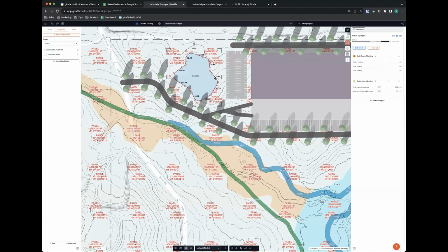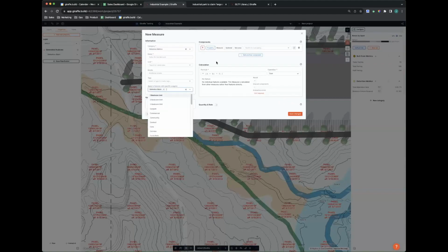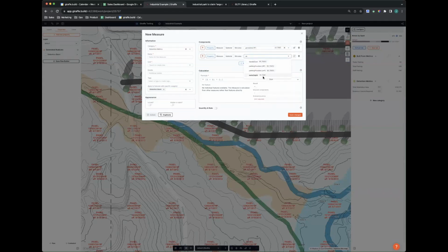And then let's go and build a calculation that tells us the total volume of water that we've catered for on the site. So we'll do a new calculation. It relates specifically to the detention basin, and it's the gross area multiplied by the depth. Now, again, very simplistic calculation. We could add in a trapezoidal calculation if we want. Again, that's probably more than we're going to need to do here on this call. And we'll call this detention basin volume provided.